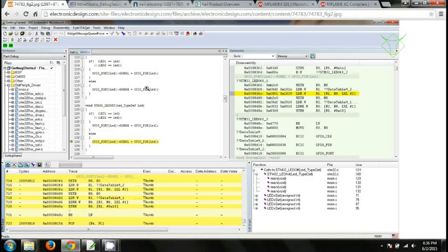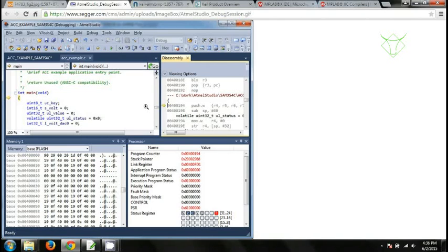IDEs. This is the IAR Embedded Workspace IDE, and most of the IDEs will look the same because it is only a text editor with features of debugging, release code, and settings like that. But the strongest part of an IDE is that it integrates everything, like debug tools and hardware tools. In case you have different tools for debugging, it can communicate with them. And in the backend you can configure a lot of things for compilers, compiler settings, optimization settings, all those things, which makes it easy. That is why we have the IDE, integrated development environment.